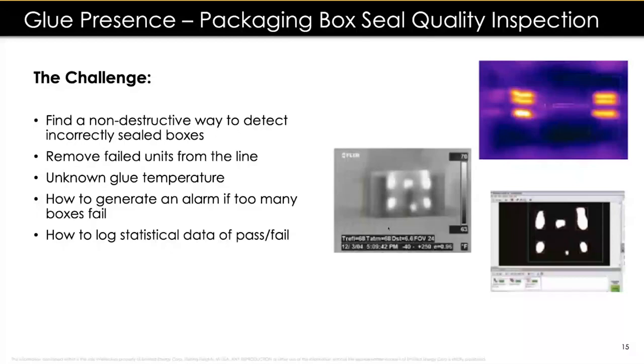And the last thing is, do we have the right spaces in between each of the blobs, so as not to oversaturate that particular product? Check. Once we've checked all three parameters, we're able to come back to the equipment PLC and say, yes, you have a pass part, you have a good part, and proceed.